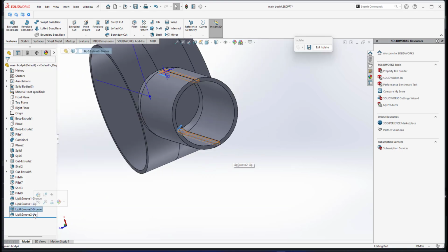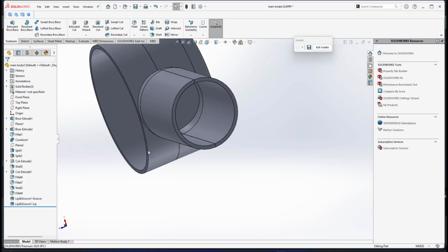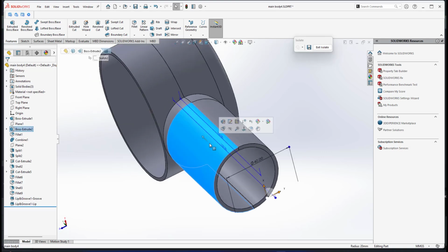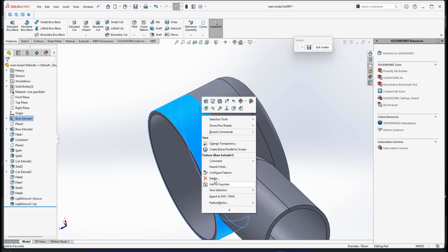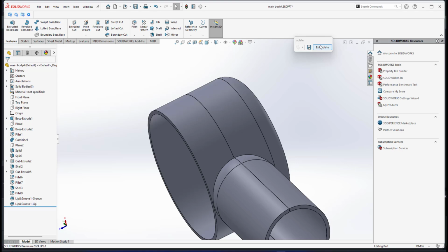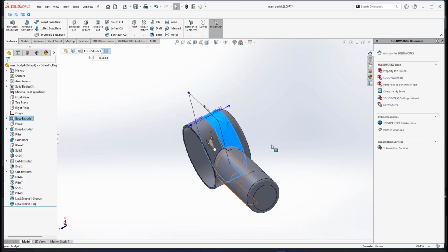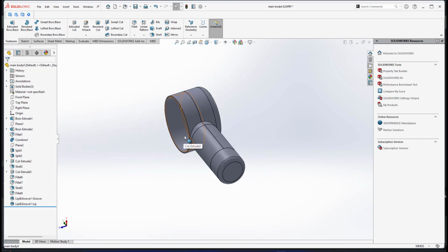So I need to do it again. I cannot do this with the standard feature lip and groove for this bottom part. This is happening because if you look at the front part of the handle and the rear part, it is a curved surface, a cylindrical surface. But for the blower unit, the front part and the rear part are connected by a flat surface. It's not a curved surface, but for the handle it is. So if we use the standard feature lip and groove, the outcome is not correct. Okay, so I need to show you how I will do it manually.